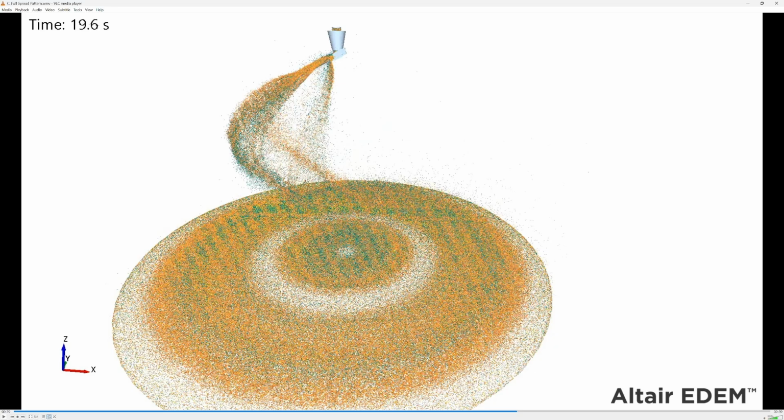We did some testing last year with a customer who had temp cables in bins, and they had 3 bins in a row. They had spreaders in 2 and no spreader in the 3rd bin. And they found that in those 2 bins, they were able to turn the fans off 3.5 days sooner because the cores were cool at the same time as the periphery of the grain. So that's some real world data.